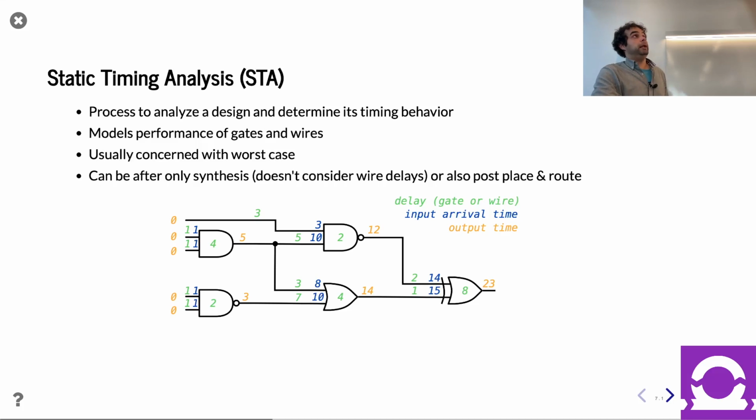Oh, good question. Depending on the implementation technology, might my critical path change for a given design? Absolutely. Some designs have a really obvious critical path, and that might not change. But most designs, if you're doing it right, don't have just one critical path. You have a few things close to critical paths, and so depending on technology constraints, that can change.